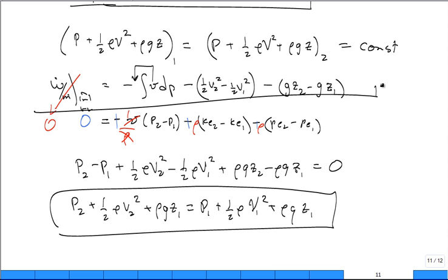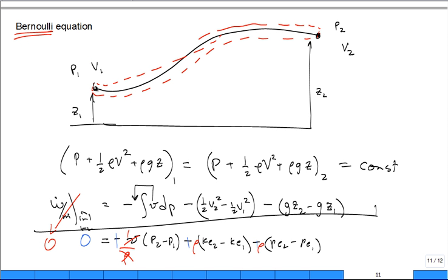You say, this is thermo. It's completely separate from any other class and any other topic. I've never learned anything like this before. But no, no, no. Here's Bernoulli's equation right at the end of chapter 6. Nice. You just have to put a control volume along that streamline in which that fluid pack is flowing, and there's no heat transfer. There's no work. It's all a balance of mechanical energy. The three forms of mechanical energy: your flow energy with the Pv, your kinetic energy, and your potential energy.